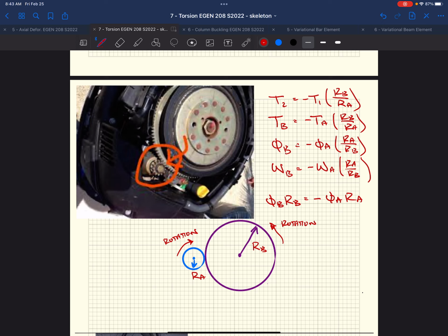as I mentioned, if this moves 3 gears, it's got to move 3 gears on the starter and 3 gears on the flywheel, right? And we know that arc length, as we talked about in the first example on Wednesday, is our rotation angle in radians times the radius, right? That would be arc length. And if this thing moves 5 radians, the distance that it moves on the outside of our circle is radians times the radius. That gives us arc length.